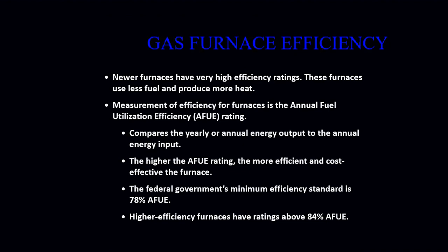Newer furnaces out there have very high efficiency ratings today. These furnaces use less fuel but produce more heat. All of our furnaces have a measurement of efficiency, and they are measured by the AFUE rating, or Annual Fuel Utilization Efficiency rating. It compares the annual energy output to the annual energy input.